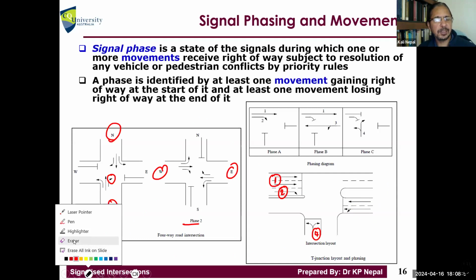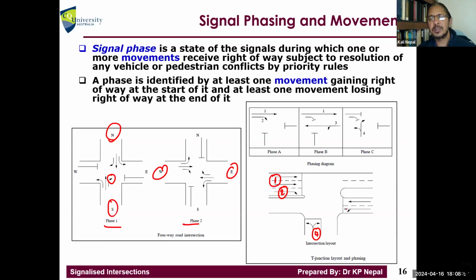These through vehicles from this lane, we cannot stop some and let others go, because they exit from the same lane, so it's better to have 3 movements. So in the first phase we stop both 4 and 3, and allow 1 and 2. In the second, we stop 2, still allow 1 and let 3 go because there will be no conflict there. And then we stop all and just allow 4 to go, because otherwise there will be conflict. That's how we need to organize the phases.